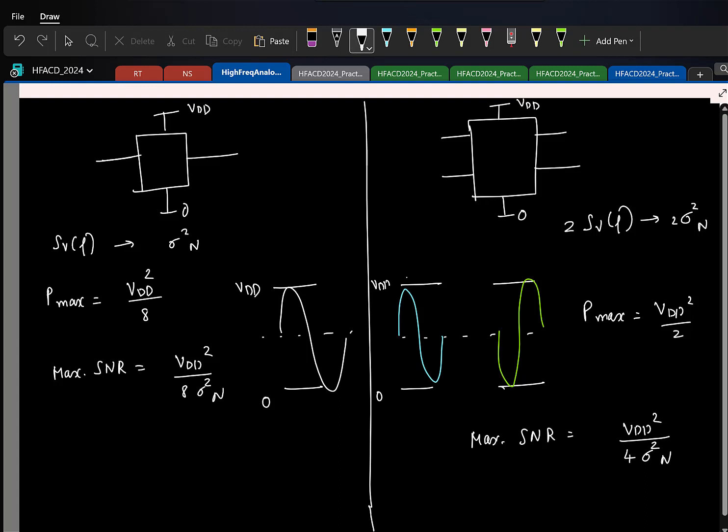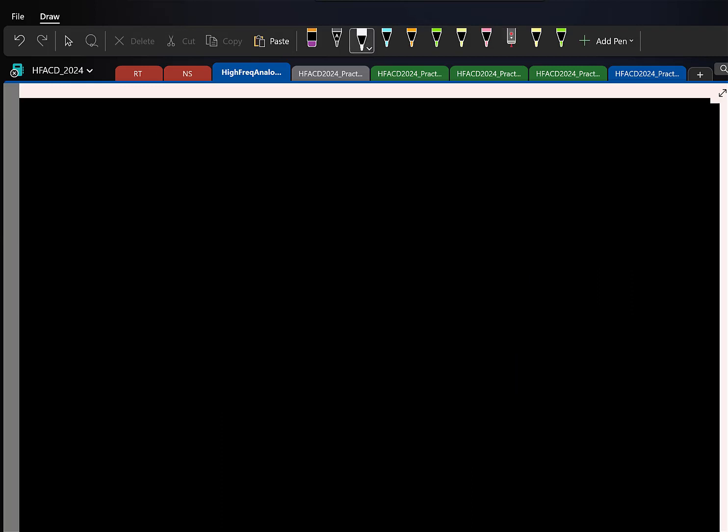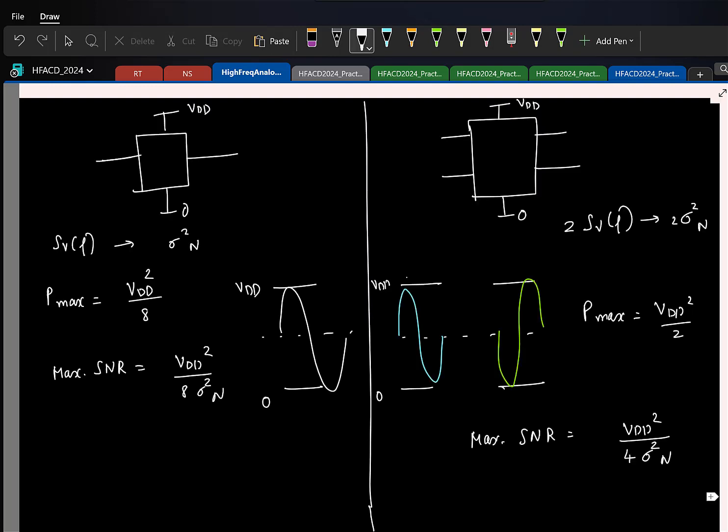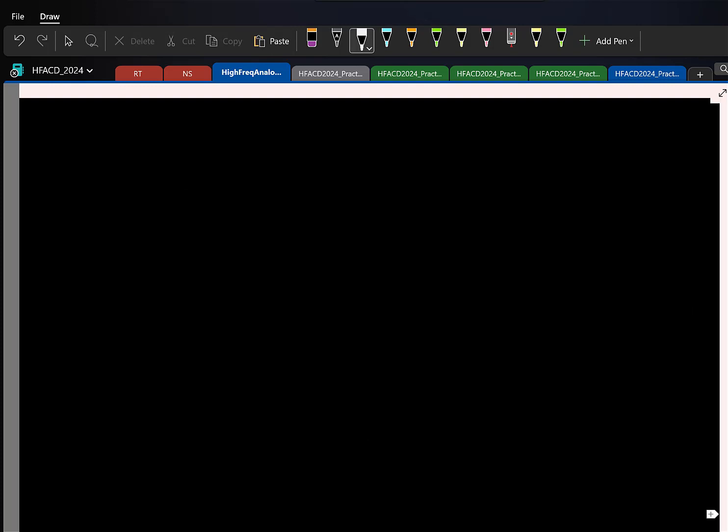So that brings us to the next part. Now, you know how to analyze the noise, find input referred noise current, noise voltage, power spectral density, and so on. That is nice to calculate and estimate. And you can also design your circuit to meet a particular noise spec, right? Let us say, in your op-amp design, I didn't give it, but maybe I'll add it now for the second project, you are given a spec that the input referred noise PSD should be something.